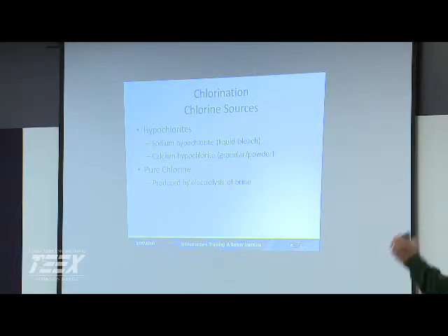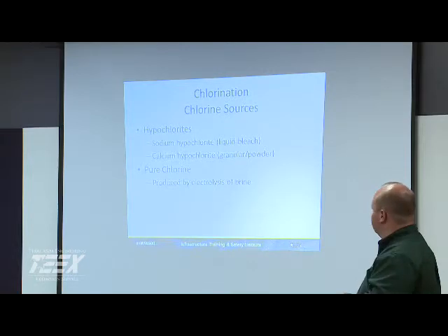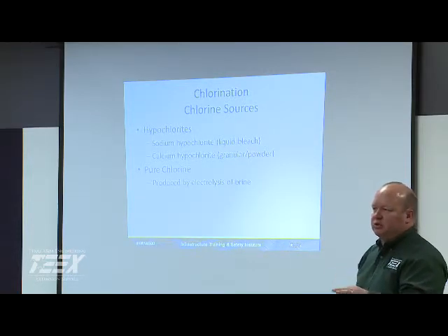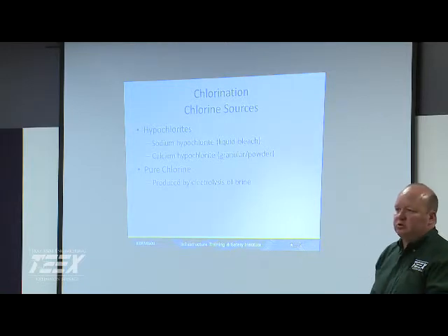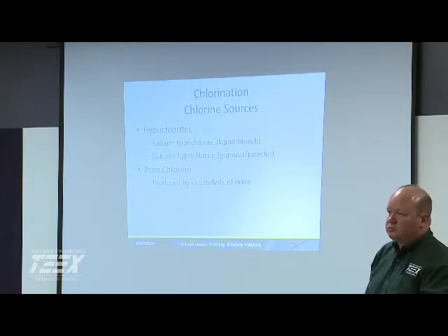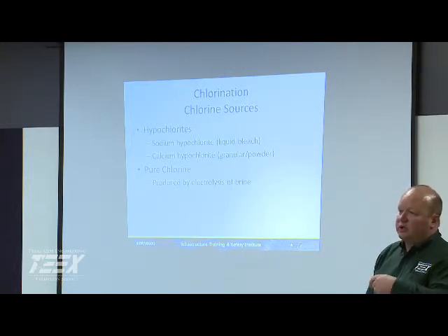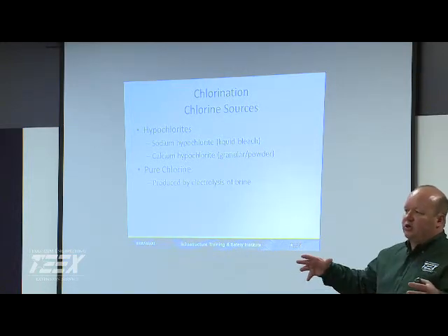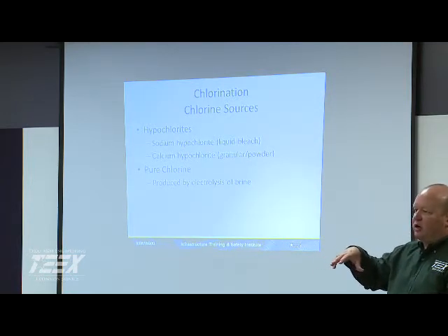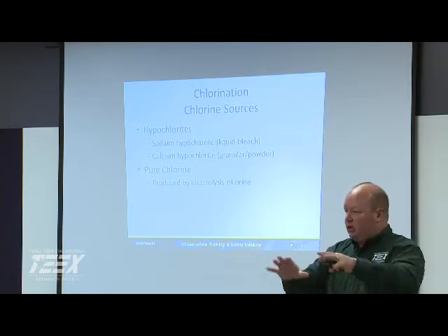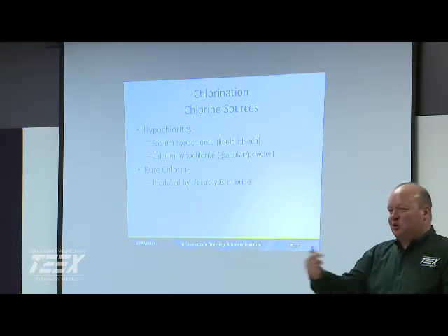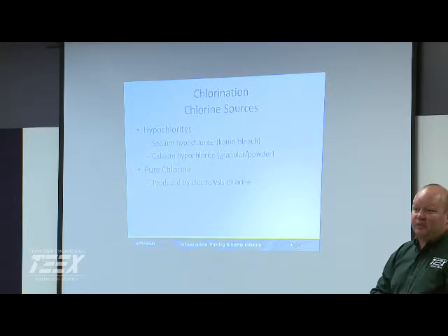When you're making pure chlorine, that's the same thing they're using for on-site sodium hypochlorite generation. I don't know if anybody's doing on-site bleach. We've got a few systems that we're doing and some systems that are thinking about going to it. I'd say it's slowly growing in popularity. We put in a system on the Riverwalk in San Antonio, at a historic pumping station down there, and they had ton containers. Of course, it's a low-lying, highly populated area, so tons of chlorine isn't necessarily the best. So they went to on-site generation.